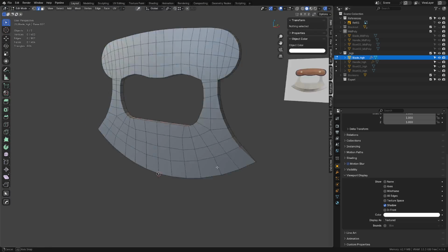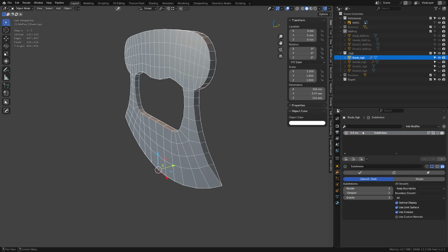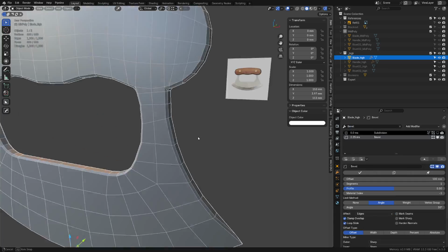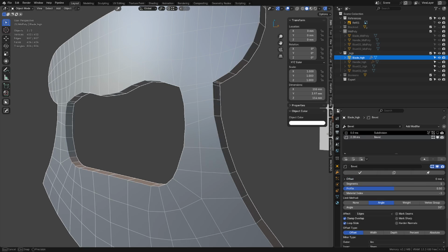All right, that's good. Now, we're going to use weighted bevels to do this, because if we add a bevel modifier, what we'll find is that bevel modifiers usually work okay. You can see we can change the outer miter to arc. It'll fix this little section, and we'll get something like that. We can change the values here to whatever we think works best. You can see it's very sensitive.